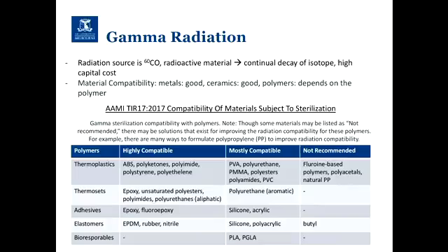So gamma radiation. If you haven't gone through polymers and polymerization, most times when creating a polymer you need a free radical. So gamma radiation can create free radicals, and sometimes that's how it can change polymers. Sometimes you'll see polymers that have just turned yellow with gamma radiation. Sometimes yellow can be okay, but sometimes yellow is an indicator that oxidation has occurred.